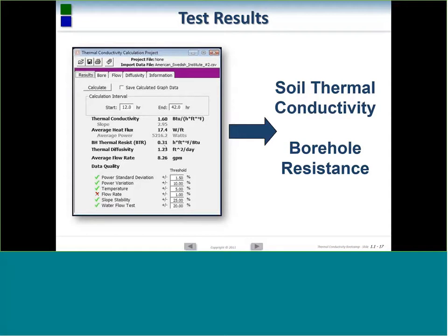But I usually caution people: unless you've done a pretty good sample of the bores and can actually establish a representative average borehole thermal resistance, shy away from using too aggressive of a borehole thermal resistance value, because you wouldn't want to ever overestimate how much energy you can move through your leach field.